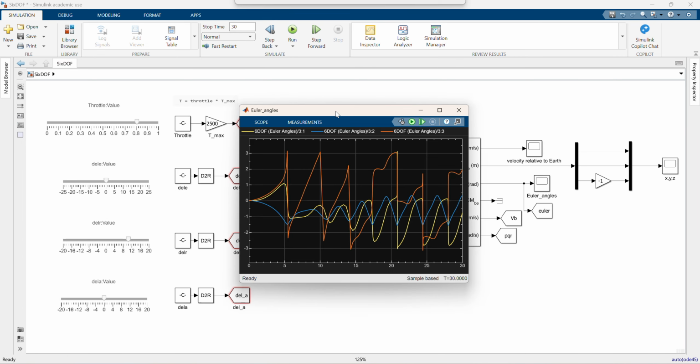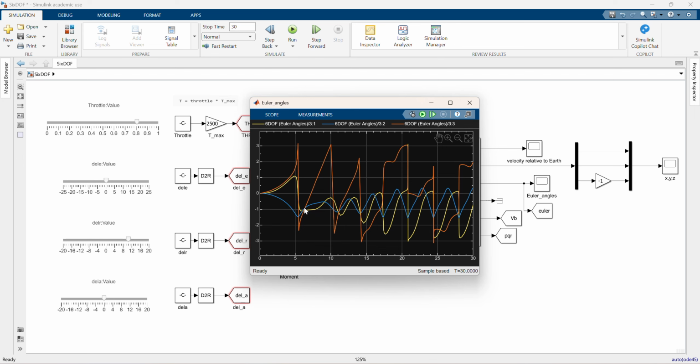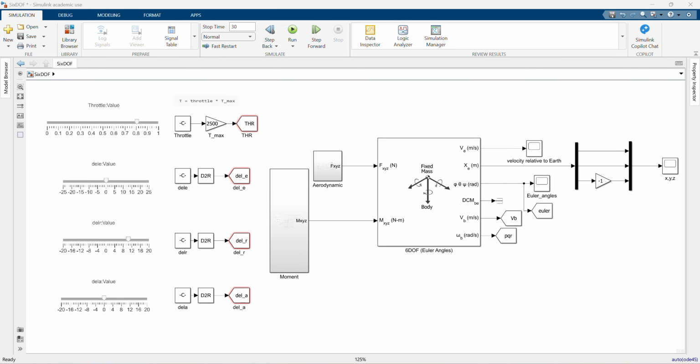You see the elevator blue one is staying pretty stable, but this psi or yaw angle is showing deflection how I want it, and then the coupling is also showing deflection with the yellow phi angle, or your roll angle. That is expected behavior, and that is your coupling taking care of it. So that's some of the lateral dynamics I was talking about.